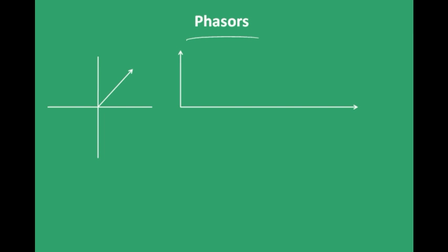Say you have a voltage that varies sinusoidally in this way. This phasor represents the voltage, and this is a phasor which rotates anti-clockwise with the angular velocity omega. So if it starts from this initial position, the position of this phasor will be this one at time t. So this will be the angle covered, and this is the phasor at that particular instant. When I give a dotted line, it will be something here. So this is the value of that phasor at omega t.